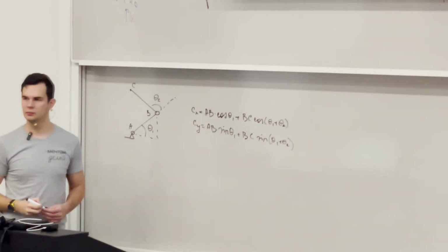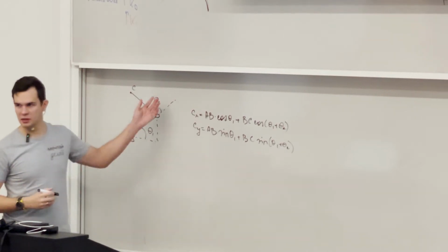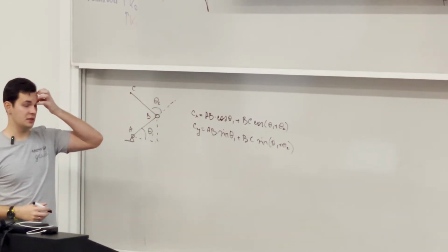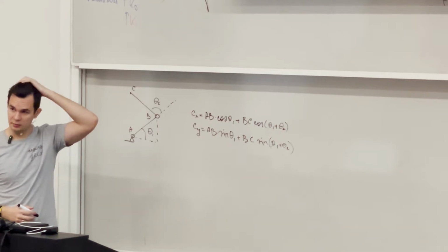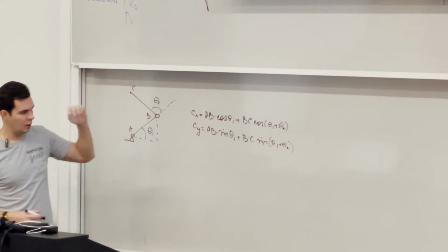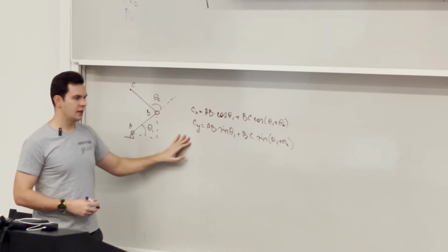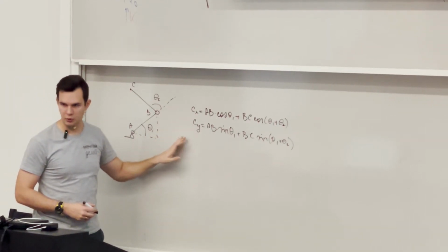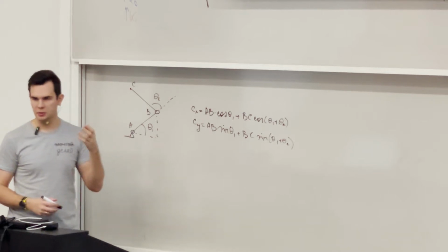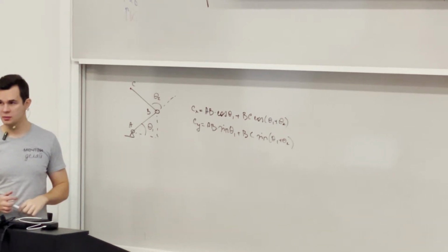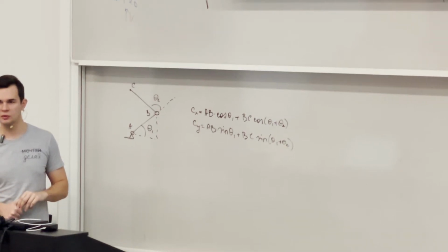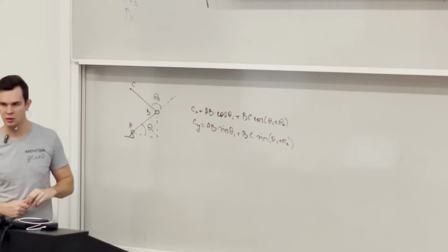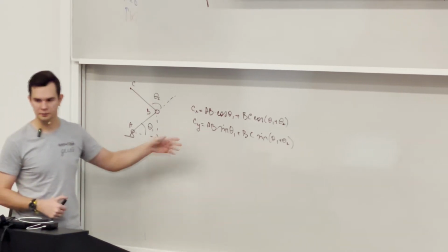Do you agree? But still, it's very basic trigonometry, and since we use explicit representation, we can take a time derivative to compute velocity. For implicit representation, it's not the case. When we cover spatial kinematics, we cannot take just the time derivative of the homogeneous transformation matrix to compute the velocities, but here we can.